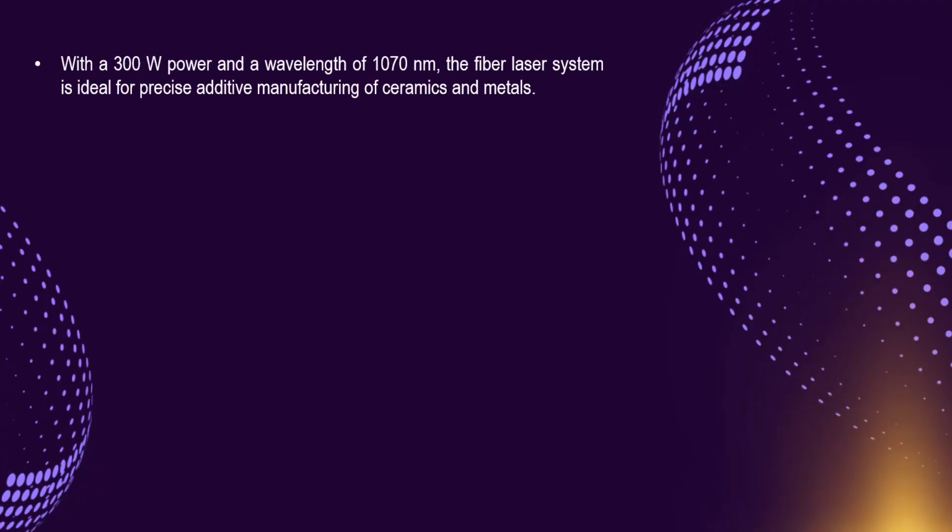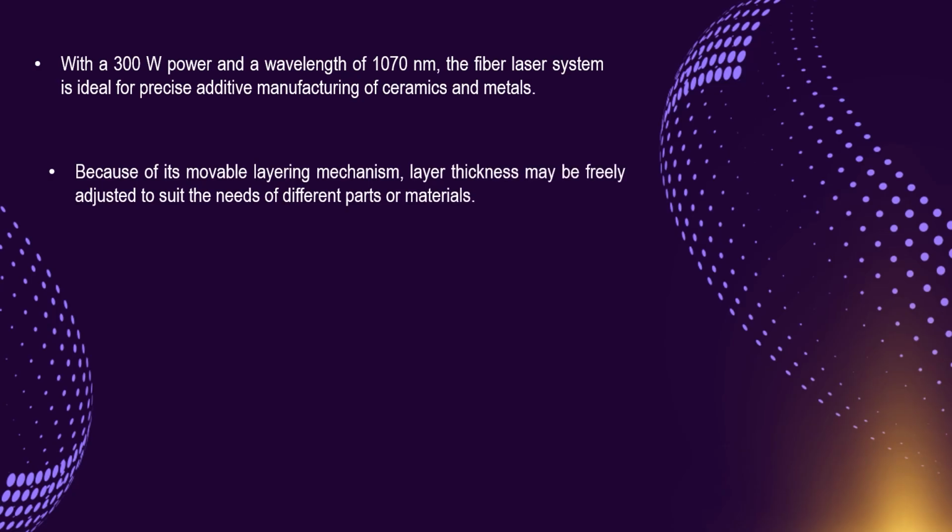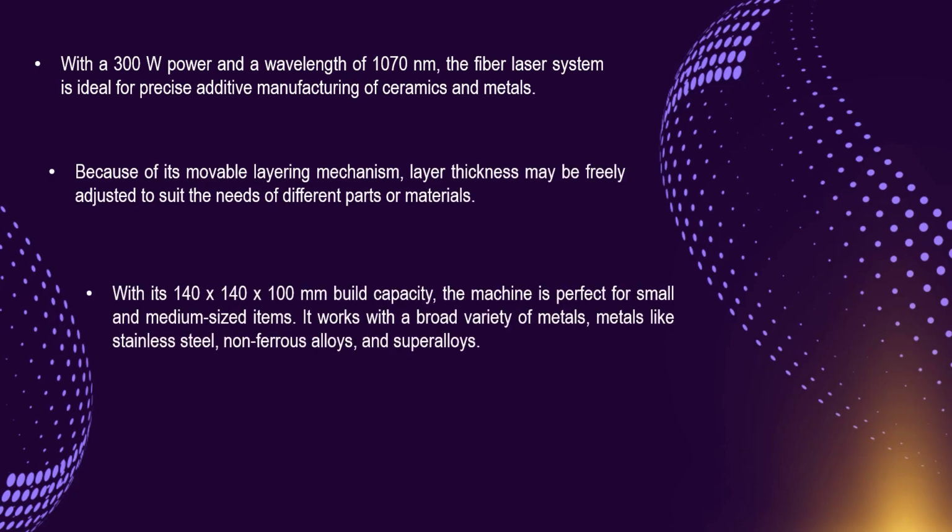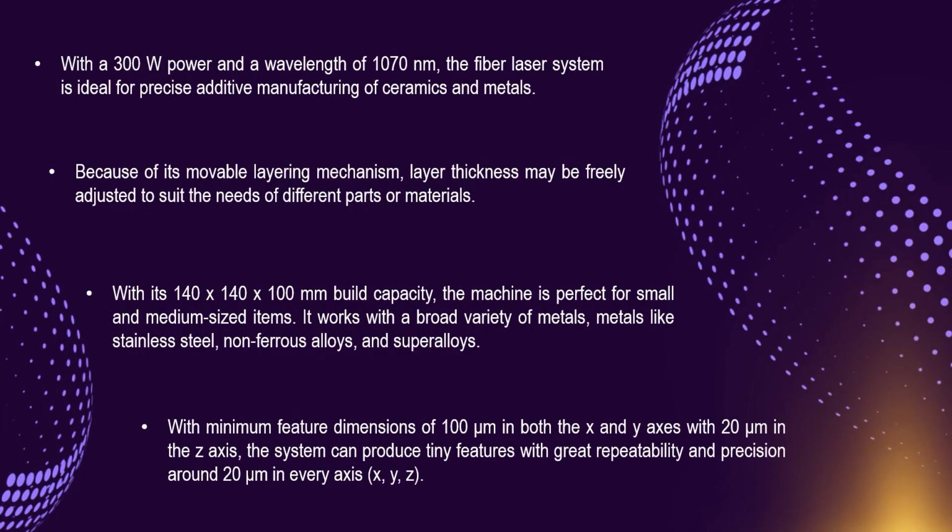So we work in the range of 1070 nanometer wavelength, and at a laser power of 300 watt. The bed size is 140 by 140 by 100 mm, and we have an accuracy up to 20 micron in x and y axis.